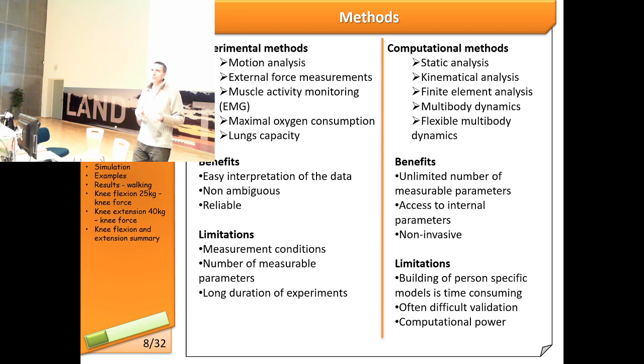Inertial properties are not that big of a problem if you get them within reasonable values. But there are other properties that might affect a lot, like for example spring stiffness for the muscles or tendons. If you overshoot or underestimate them, then your model might behave weirdly. You can walk like on the moon, or you can fall down while standing, not having enough forces. So some parameters are really critical, because they might change your results. And to establish those parameters, usually you have to use some sort of experiments to get some measurable quantities, and then you combine both approaches, computational and experimental, to get something working.